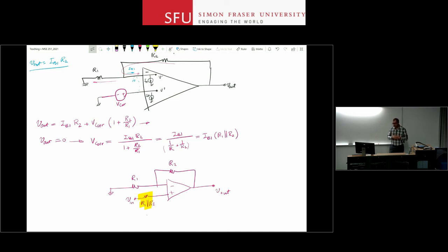And then if it is a limitation, again, there are op-amps out there whose outputs are called rail to rail. They go from the positive to the negative supply, all the way in that range. And you can choose one of those op-amps. And as always, there's give and take, right? You get one property, you may lose something else. But there are op-amps in these situations that you can go and pick.